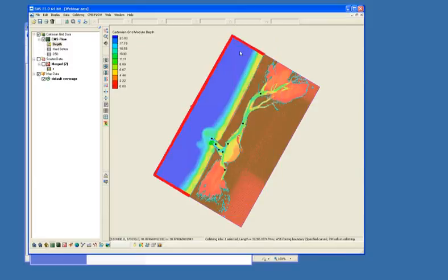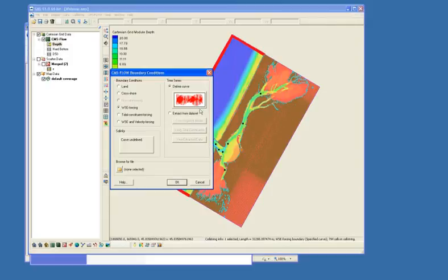They're only representative of a certain point that's in a nearby area. It may not be the best way to do this if you have an extremely large domain. There are tidal constituent databases that are available for the east and west coast of the United States, as well as the LeProvost database that's available for anywhere in the globe. And if you want to use constituents from that database, you can use,